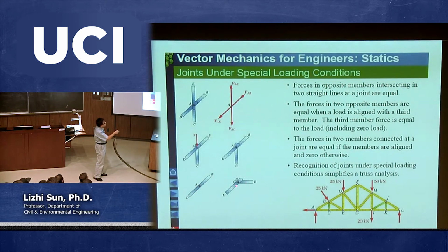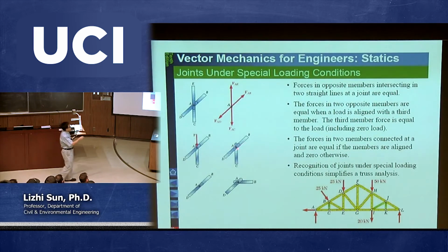If this is the case, then immediately you can say the internal force of AD and internal force of AB are both 0. That's called the zero force members. Okay, if you encounter this case. The other case, which I want you to understand, is having 3 members connected with the joint, and there's no forces. And among these 3 members, 2 of them are in one direction, in 180 degrees. Then the third member should have 0 force. So that means you don't have to cut. You can conclude the internal force of AC is equal to 0.